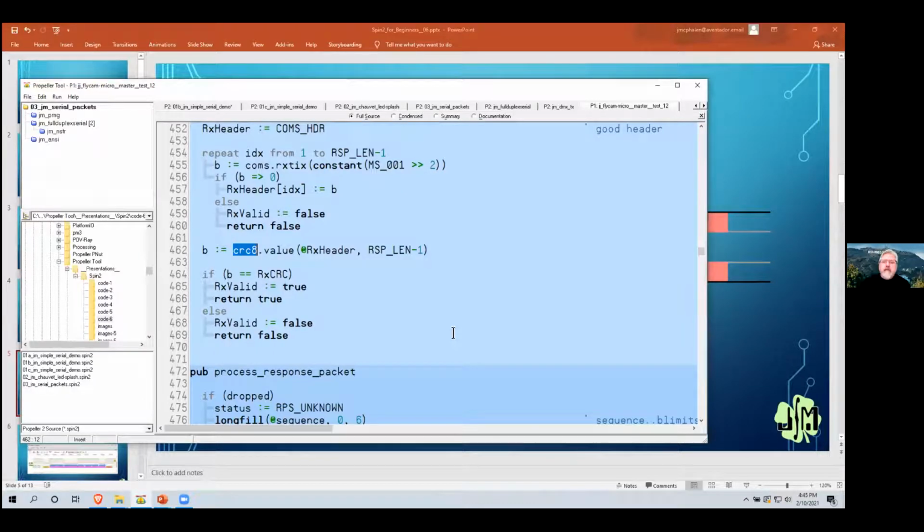So if, for example, we put term.tx parentheses 65, it's going to put a capital A on the terminal because 65 is the ASCII code for the letter A. Now we could put A in quotes. So that's a representation, because I see sometimes people want to send a single byte, but they're actually sending a string representation of it. So you have to be aware of that.